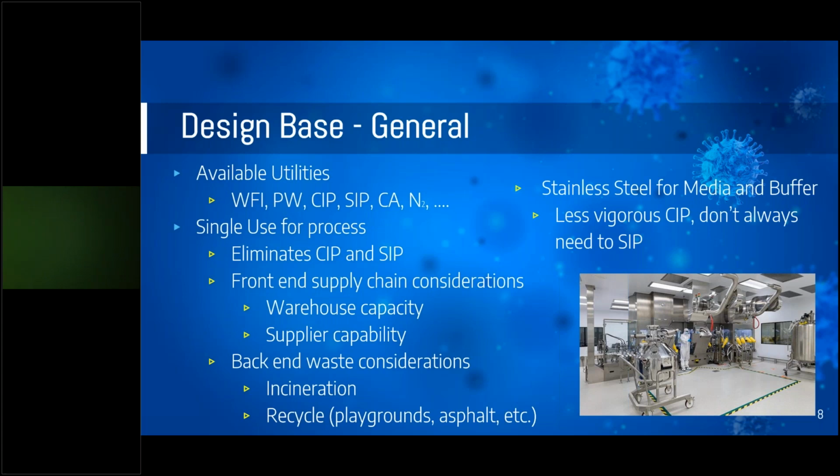While single use is great for saving on the cleaning and sterilization aspects, there are also some things to be considered when taking on single use, particularly on the front end and back end of it. On the front end, you need to make sure that you have capacity to store and hold all of your single-use materials: all of your bags, tubing, connectors, etc. Now, because we assumed that the design of this facility was already completed, we assumed that that consideration of having the warehouse capacity was part of that design. And so that's not something that we really focused on because we assumed it was taken care of already.